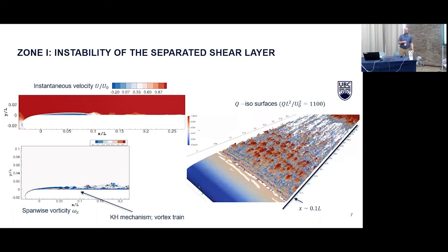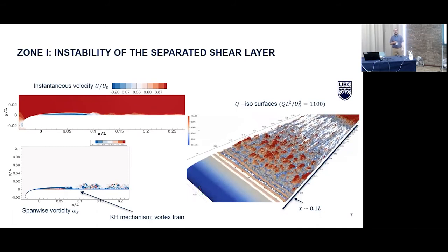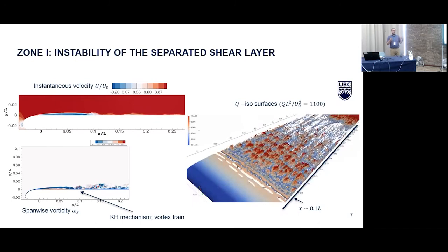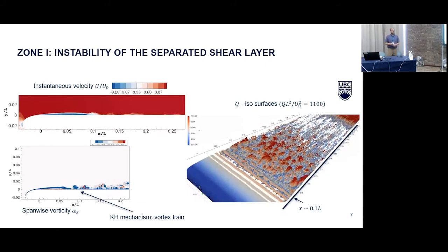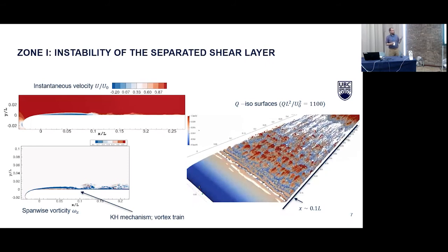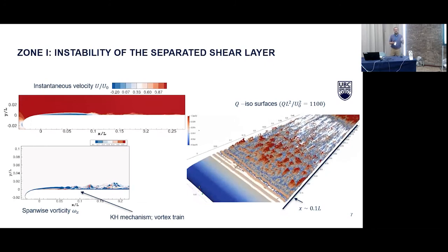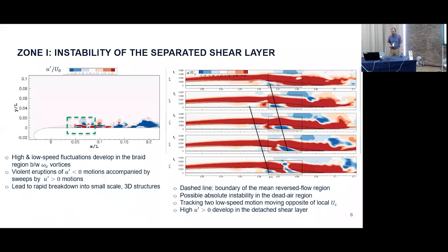We have hairpin vortices that spawn subsequent hairpin vortices that spawn subsequent hairpin vortices, and we'll see this has a significant impact on the near-wall momentum exchange and creation of turbulence downstream, really close to this leading edge. So even at this point, we can say the importance of resolving the blunt leading edge is quite significant, and neglecting that might have deleterious consequences.